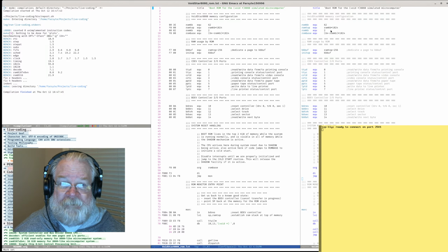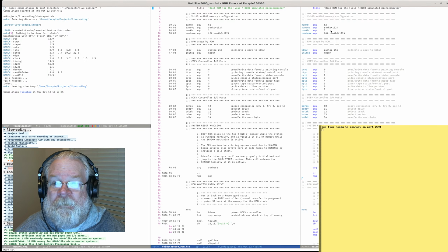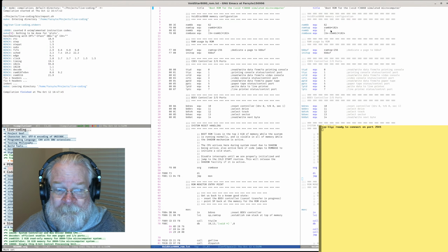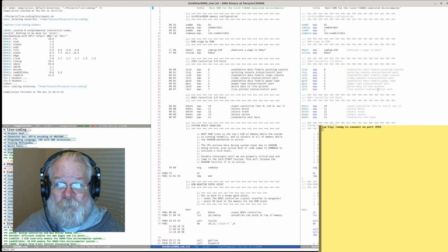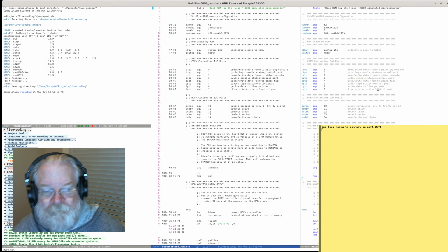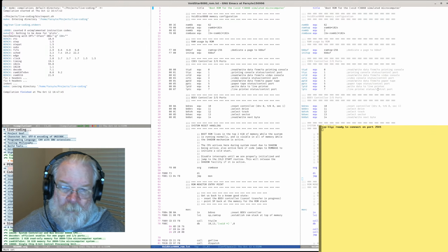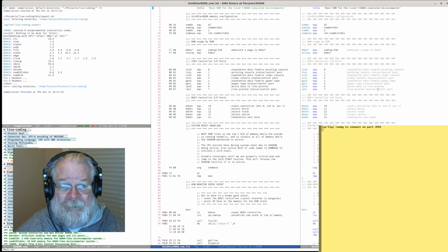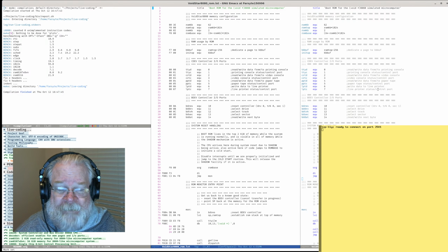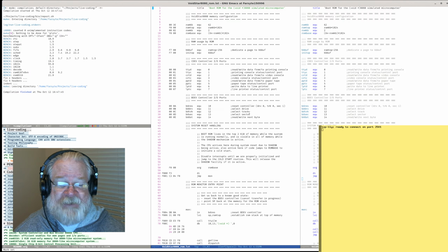And I am changing some of my plans. I've decided that I only need 2 kilobytes of ROM. In reality, I probably only need like 32 bytes of ROM if I'm really honest. But for now, I'm going to do a 2 kilobyte ROM, and we're going to put a ROM monitor in it. Long term, the only thing the boot PROM does is yoink in your boot sector from your boot disk and start it going. And you might have a boot disk for CP/M and a boot disk for Forth and so on. That's my plans long term. Short term, however, I do want to have a boot ROM that has some kind of ROM monitor in it. And we'll see what I've got as I put it together.